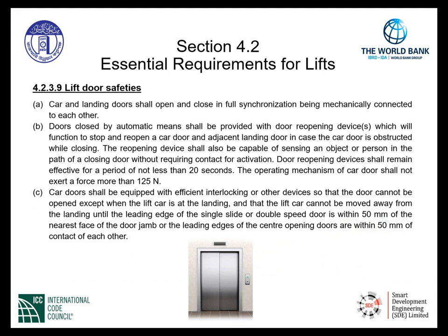Lift door safety requirements are indicated in section 4.2.3.9. Item A requires that car and landing doors shall open and close in full synchronization, being mechanically connected to each other. B, the doors closed by automatic means shall be provided with door reopening devices, which will function to stop and reopen a car door and adjacent landing door in case the car door is obstructed while closing.